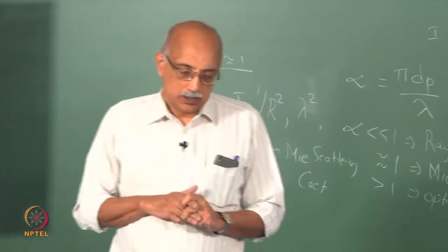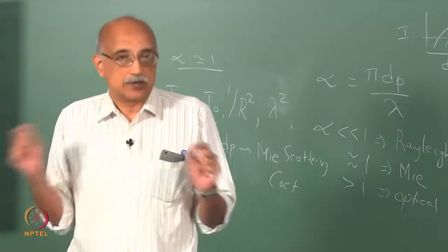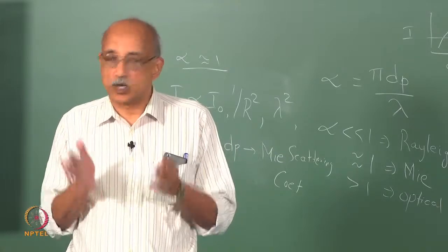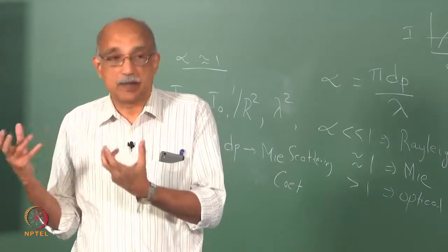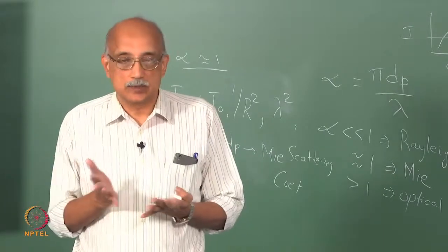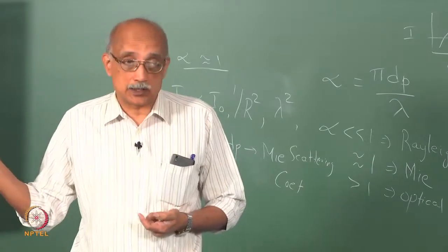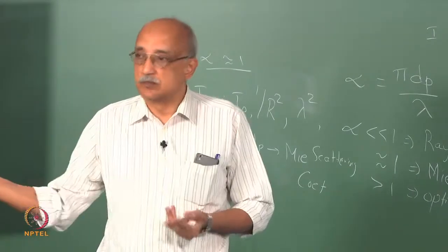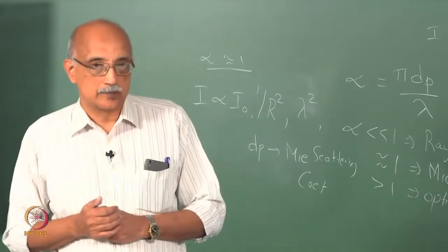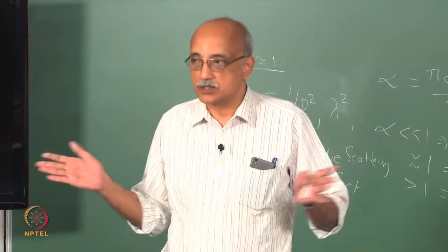Now, what we have been talking about so far is measuring sizes of individual particles, but in reality in nature or manufacturing processes you very rarely have particles of a single size unless they are specifically manufactured that way for some purpose. So, the kind of particle size distribution you see is what we call polydisperse. In other words, there are a variety of particle sizes that can extend all the way from nanometers to millimeters, covering a very wide size range. So, you want to be able to detect particles that are not only in a certain size, but particles over a fairly wide size range.